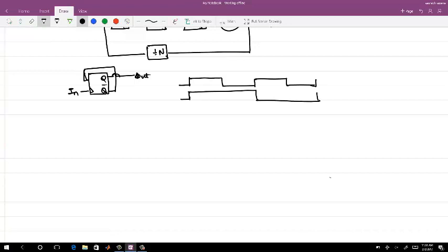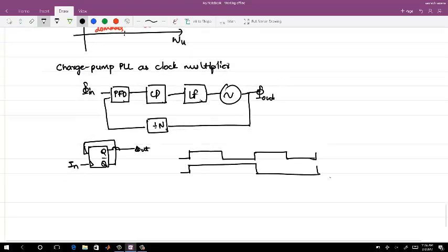Let's say there is a delta T error at the input of the divider. The delta T error will not change at the output. It's absolute time. If I shift the input clock by delta T, the output clock will also get shifted by delta T. The divider itself is not adding anything to it. But now that delta T is introduced at the output, the output frequency is half, so you refer to the output frequency because the phase is always with respect to a frequency.